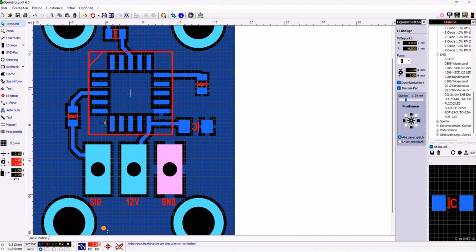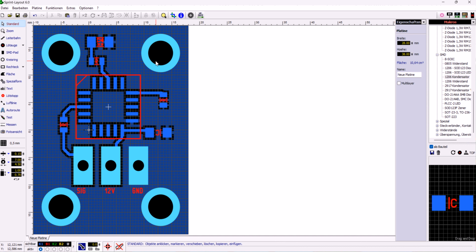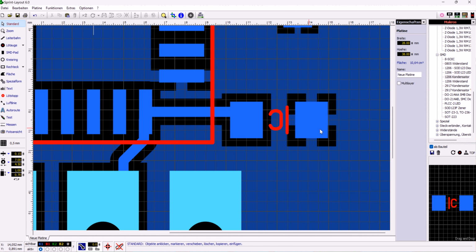You can, as I said, either connect it by setting the clearance to 0 or by using a thermal pad. These mounting holes, it depends on whether you want to have them grounded or not, but maybe we won't. So for mounting holes, I would always not use thermal pads. If they should be connected to ground, I would always put the clearance to 0, because usually you don't solder on them, so there's no question about it. Of course setting it to 0 is a better grounding method than this one, but you do it here because usually you don't have too much current here. But it's good to enjoy the benefit of easier soldering because you don't take all the heat away. That's why it's called a thermal pad.